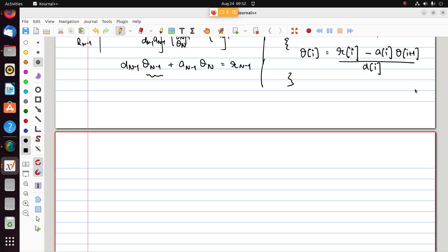If you have a certain number of parameters, with non-dimensional equations you reduce the parameters typically by 3. That depends on the number of fundamental dimensions you have in the equation. But the process of non-dimensionalization makes things much easier for us to handle.